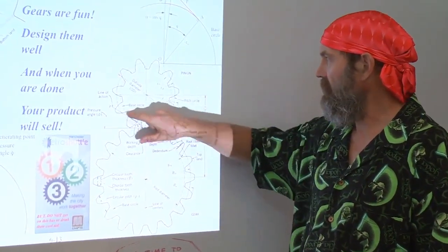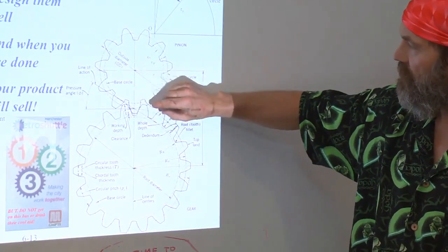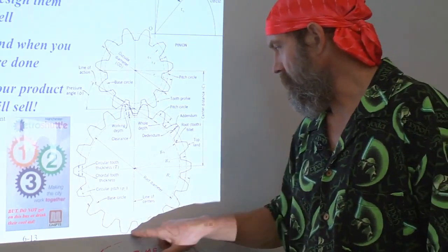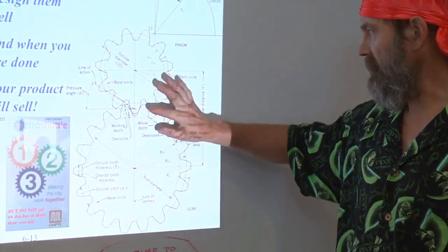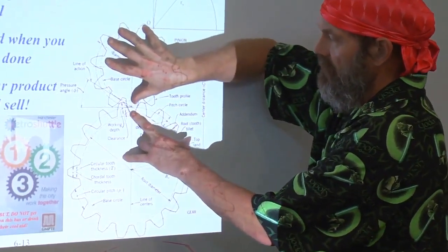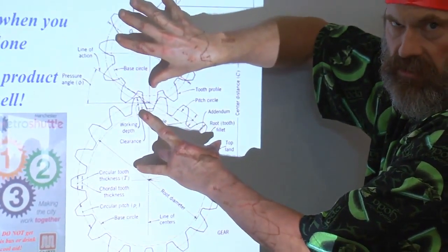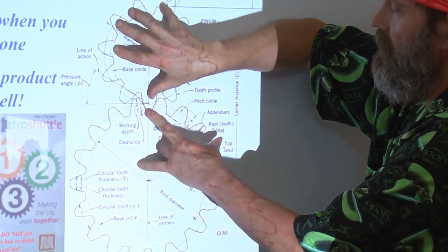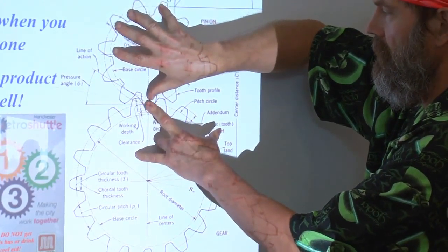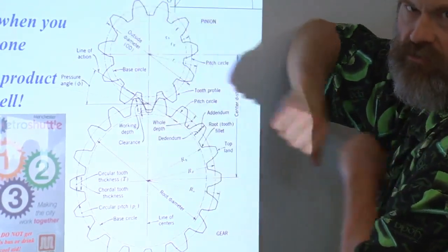And that is, if I have one gear and another gear, the effective contact radius of the two gears happens at what's called the pitch circle, which is roughly what's going through the middle of the tooth. This is a spur gear shape formed by this involute. There are other specific types, but nominally they're all based on this unique property you're about to see. And that is, if the gears are moved apart a little bit, it doesn't matter with respect to the transmission ratio you'll get.